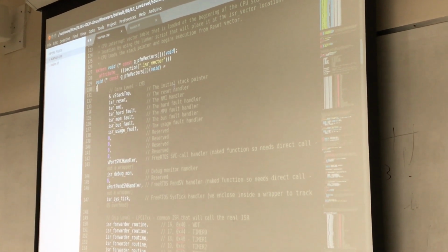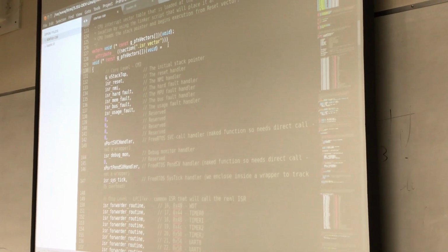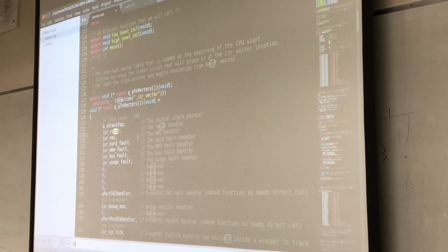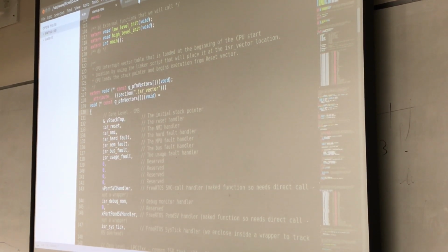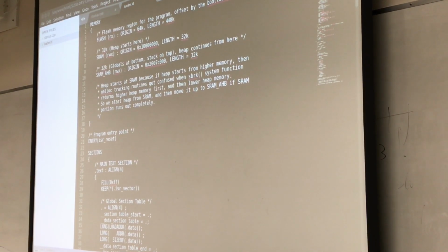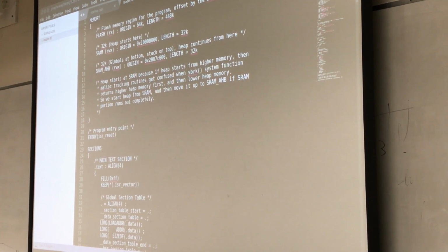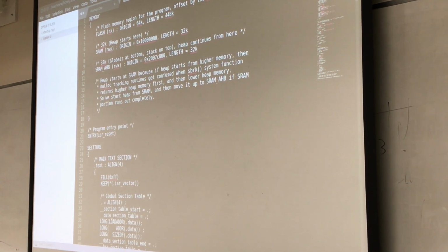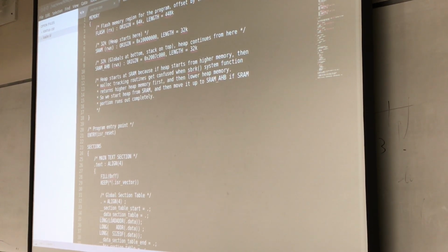Now your startup.cpp said something about section .isr_vector. To understand why this attribute has been given, we need to look into another file called loader.ld. Can you open up loader.ld? It's not inside any of the L folders. It should be outside of that, in the folder that holds L0, L1, and all the rest. It's one parent up.